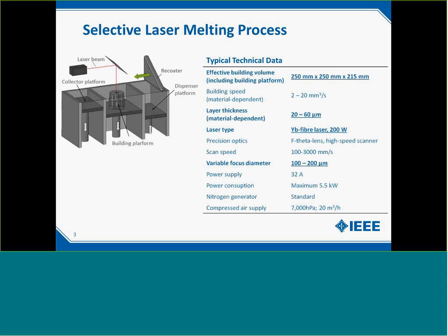In the laser melting process, the part is built over a building platform, where a coater spreads a layer of powder. Then a laser is used to consolidate the traces of interest in that layer. Then, when the layer has been processed, the building platform is lowered, and a coater will spread a new layer of powder. All these steps are repeated until the complete part has been built.